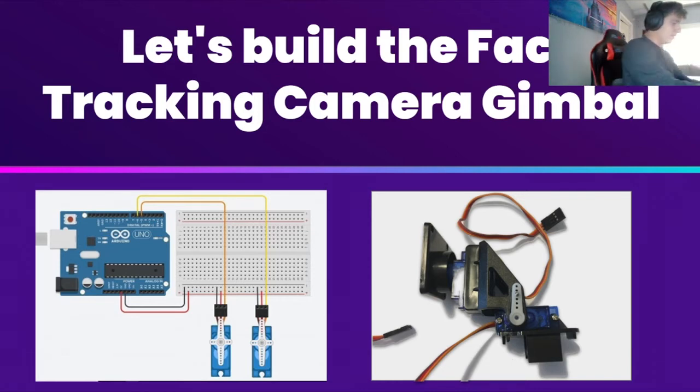So I'm going to be using these right here, but if you have scissors, you could use those too, but again, just be careful. What you're going to want to do is leave the three holes that you have here, because the screw you're going to be putting in is going to go on the third hole. So make sure not to cut that third hole. If you can, just cut it a little bit above the third hole, and that should allow it to enter the gimbal and then you can put on the screw. Be careful with your eyes or anything around you. It may go all over the place.